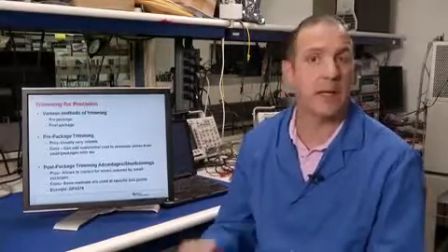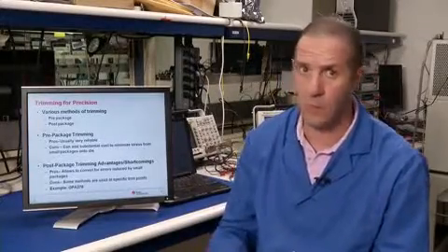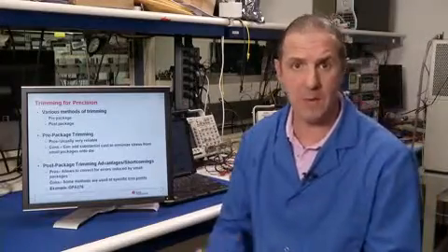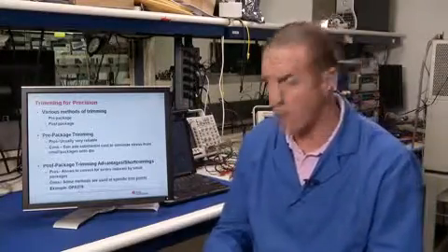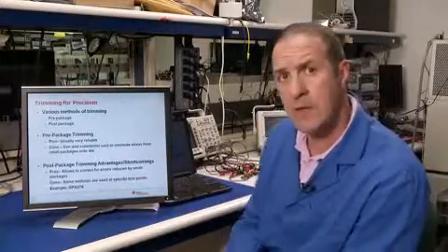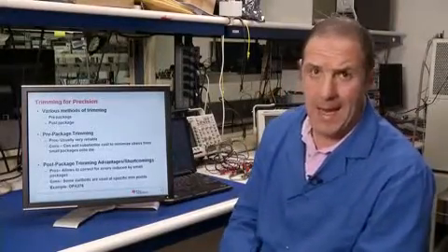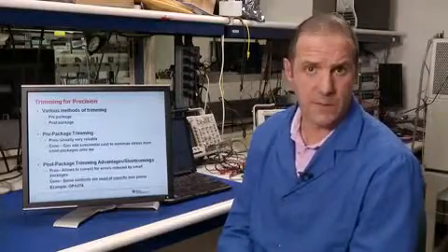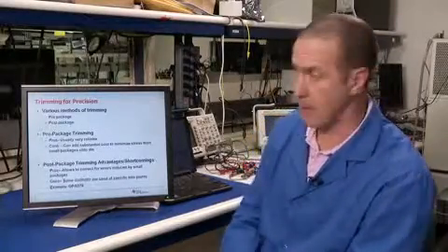So ultimately, it is you, the end user's choice, to look in a data sheet and determine whether or not this is applicable and this is suitable for whatever application you may be considering this device for. An example of a post-package trim method would be something like an OPA376 built on a pure CMOS process at 5 volts and achieving 25 microvolts of initial offset max at room temperature clearly.